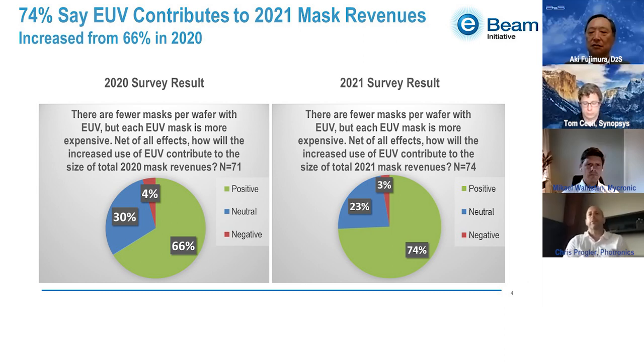On the other hand, complexity definitely brings more challenging manufacturing conditions. The tools are generally more expensive. Inspection tools cost more, the repair equipment costs a bit more, everything on the equipment side. And complexity also tends to drive yield in the wrong direction for mask making. It has to do with dispositioning and defectivity. So you often get a negative impact on more complex masks in yield, first pass yield, regular yield, and hence cycle time.